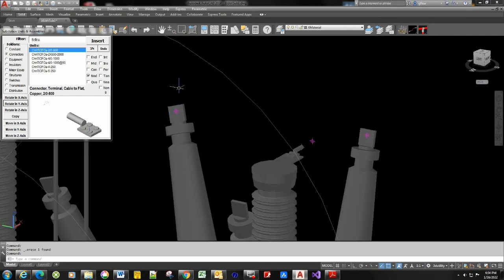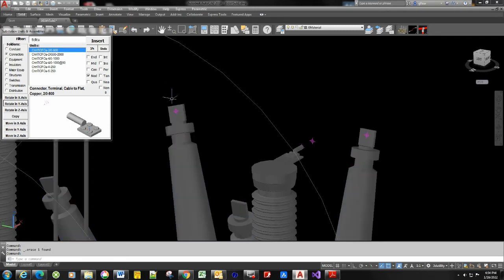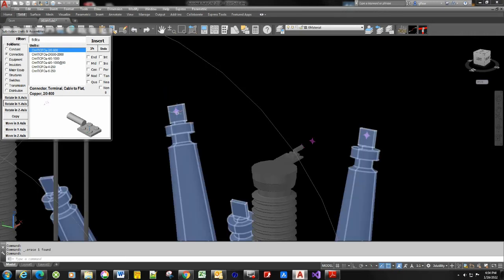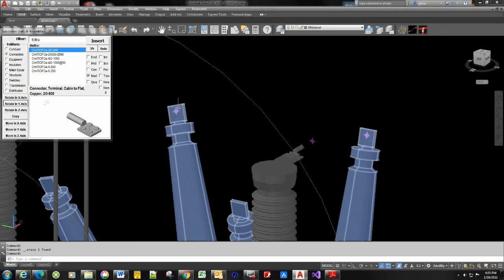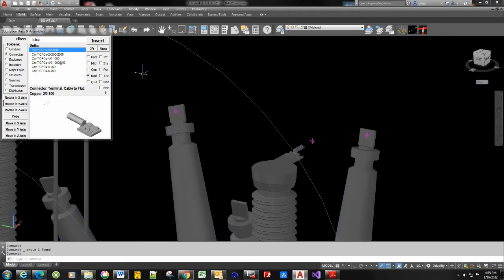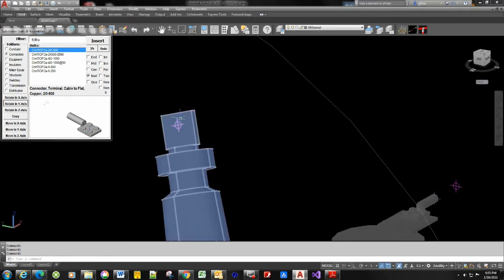So in the former video using BricsCAD, we were able to take advantage of the dynamic UCS that would find the plane of that pad. Unfortunately, AutoCAD has a dynamic UCS mode, but it will only find the plane of a 3D object. And since this 3D object is embedded within a block, it won't find that. It's because it's embedded.